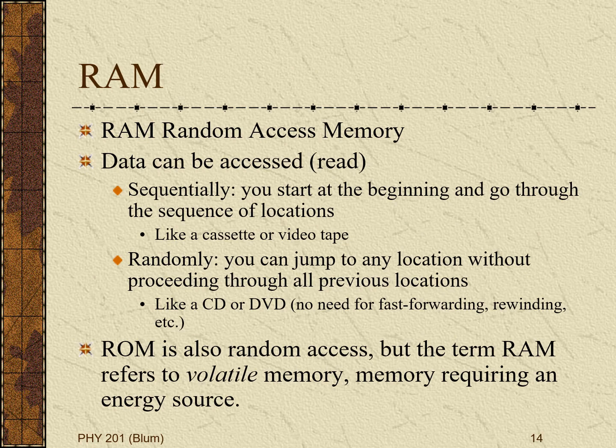Now, the alternative to ROM is RAM, Random Access Memory. So let's see what the term random access means. Random access refers to how the data is accessed, how it is read. And so we distinguish between sequential access and random access. So sequential means you go in some particular order. The example for that is some kind of tape.